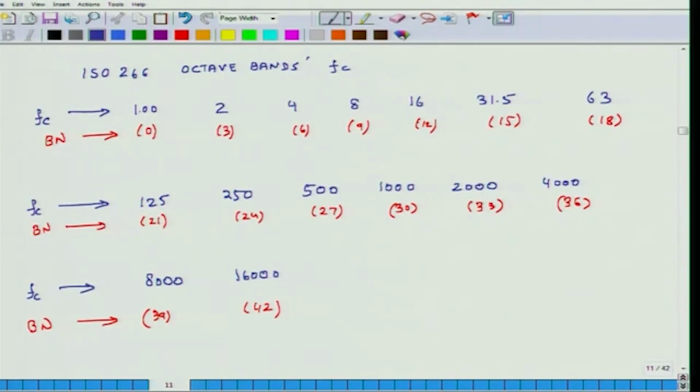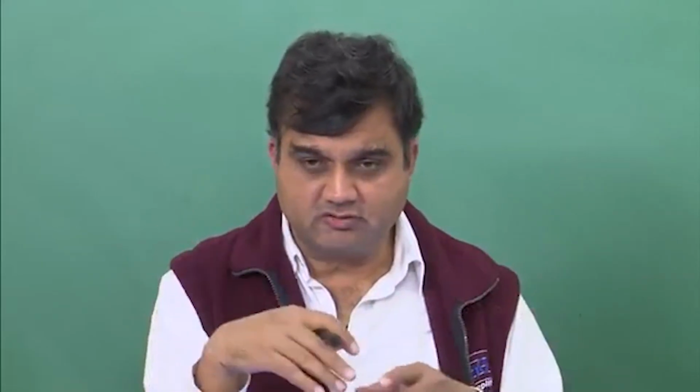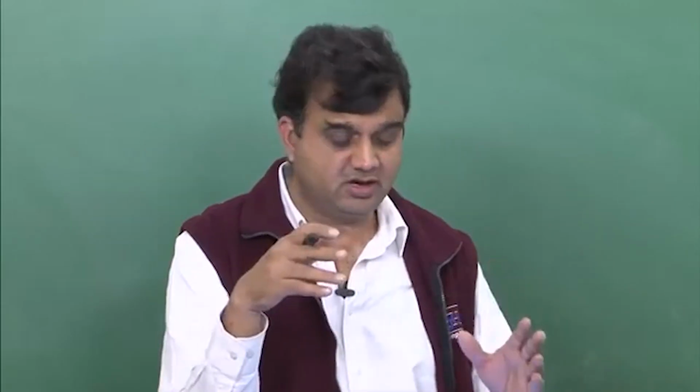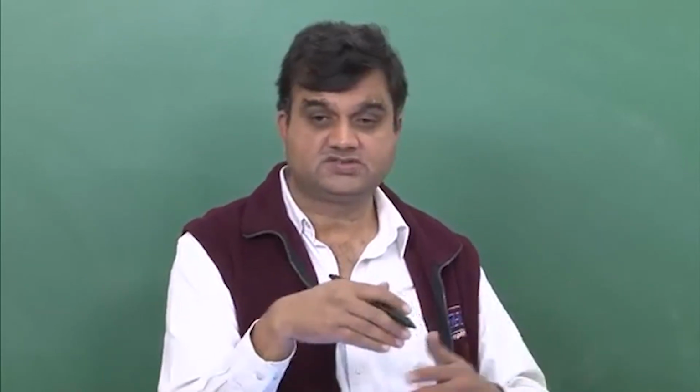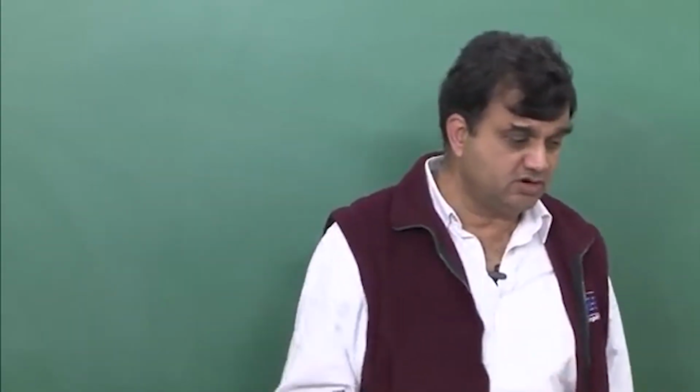Okay, so a lot of times in the industry or in scientific literature, you will be expected to produce your results related to noise measurements, and initially you will have time series data, then you may FFT it, and then the expectation will be that you further change the form of that frequency domain data and you report data at these specific center frequencies only. Okay, because then you can see cleaner information. There will not be 20,000 points, there will be cleaner information and people can compare your results with their results. How you do that, we will discuss later. But right now, this is what I wanted to discuss.